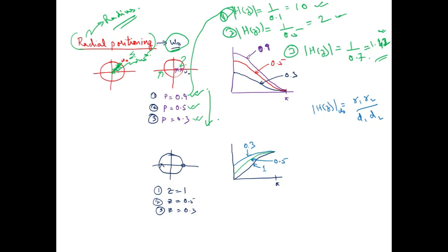The same type of activity can also be observed if you change the radius, wherever you want to go. So at the resonant frequency, you will be getting a similar type of thing. Since we have placed it on the positive real axis, we have basically designed a low pass filter.